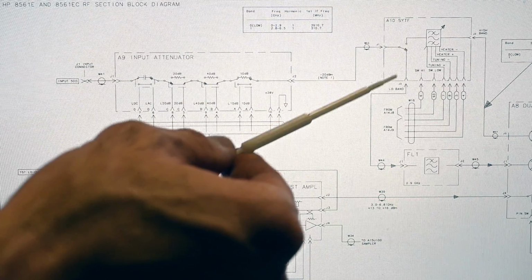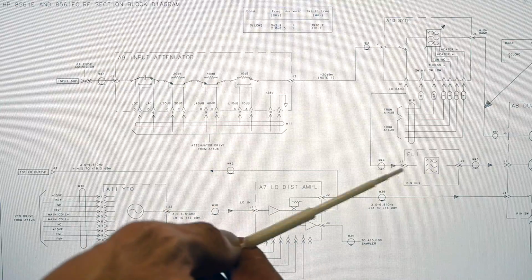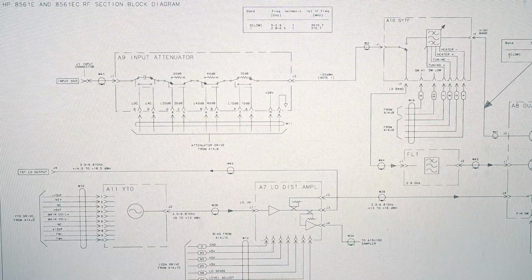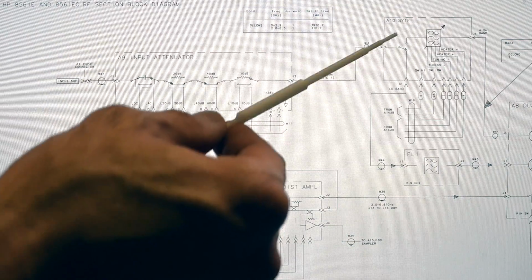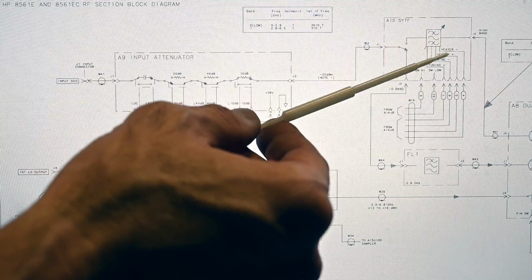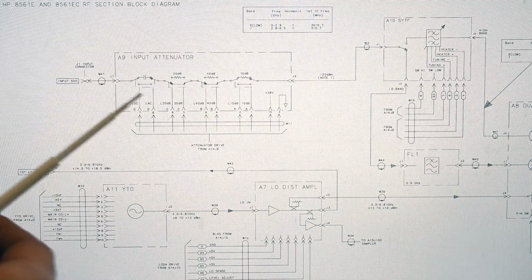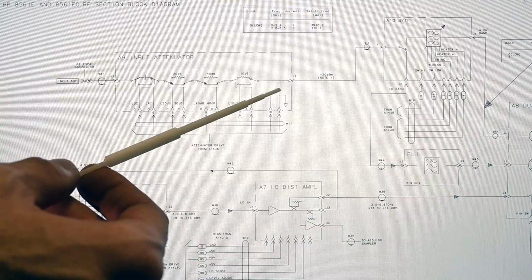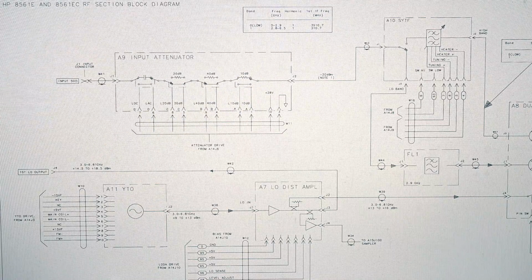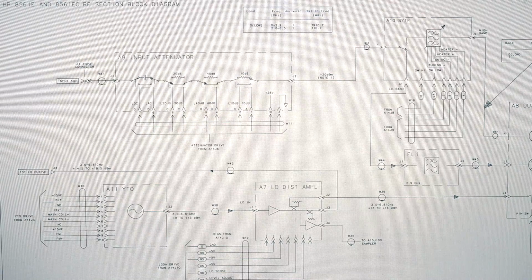If that looks okay, then we'll continue and move over here. Maybe this filter has an issue, or we'll have to continue on down the RF path. But I think this would be a good place to start, and let's take a closer look at this, because again, we know this is functioning correctly, so we can go ahead and pass the signal through this attenuator. I'm not worried about that now. So let's go over to the other spectrum analyzer and we'll get things set up.